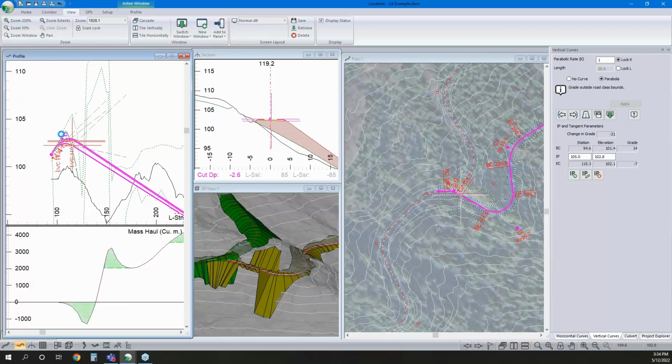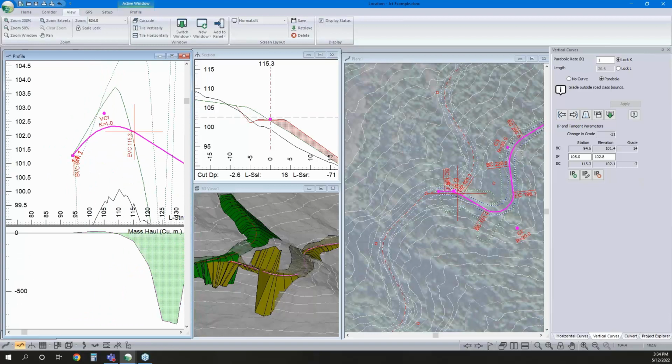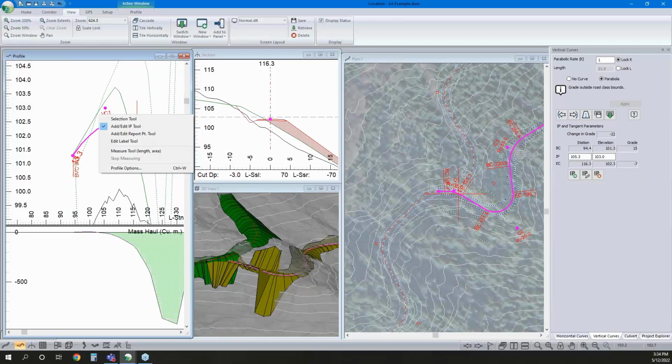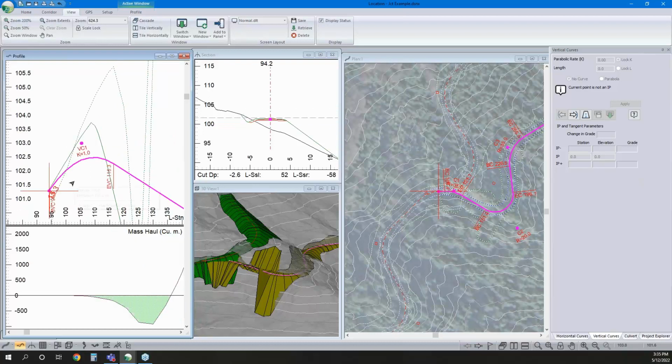And if I wasn't properly accounting for where that other surface is, it would be really easy to say, well, we're tying in at that elevation, at that gradient, and we've got our vertical curve, and away we go. But now we can click through and see that if we actually built this as is, we still need some work to get the proper separation between those two alignments so we don't end up severing access or undermining something that we want to preserve.